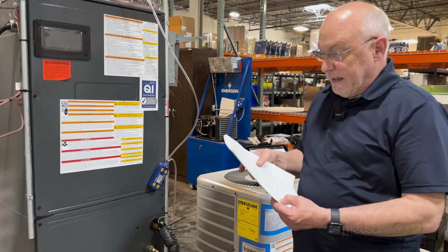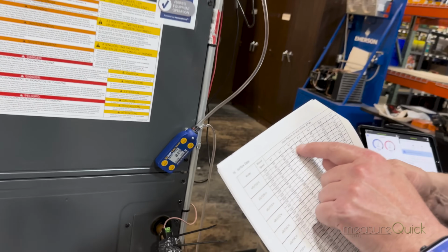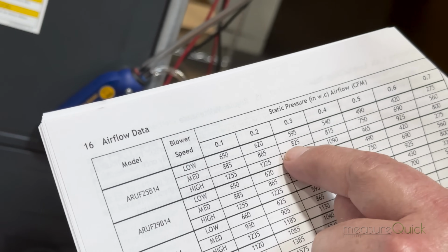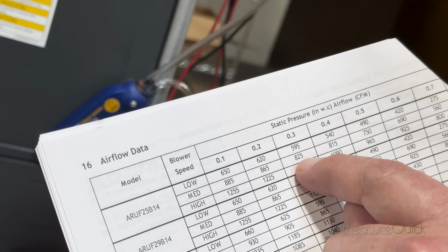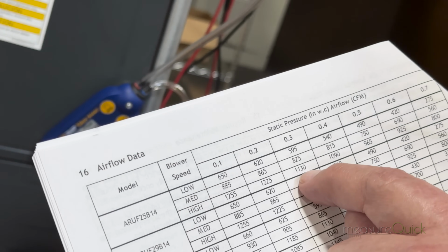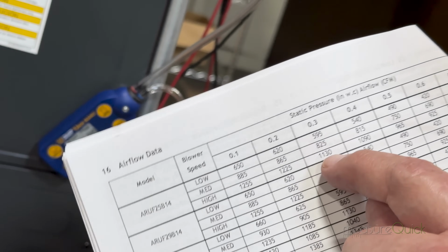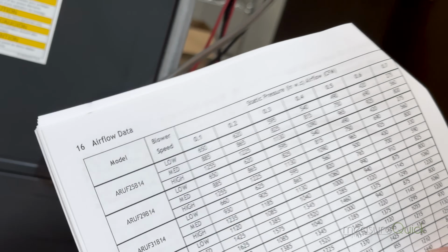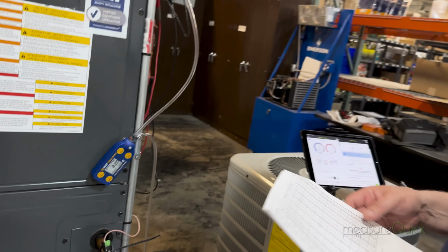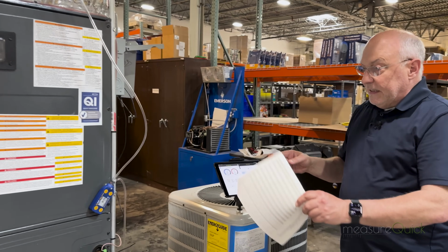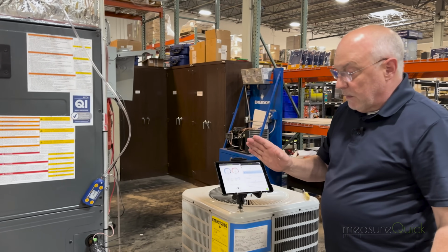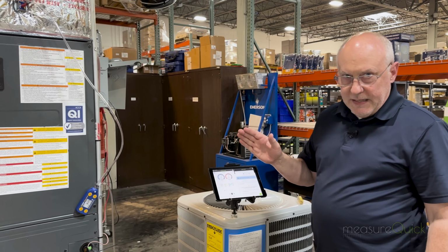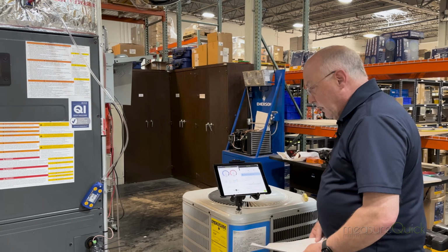If you look at this chart again here, you can see low is in the 600 CFM range. So this would be for like a 1.5 tons. Medium is about a 2-ton, and then we get up to 2.5 tons here on the high speed on this system, or maybe closer to 450 CFM per ton. So now that we have all those things done here, we got airflow correct, we're in the ballpark anyway. Now we're in a position that we can actually check the charge on the system.